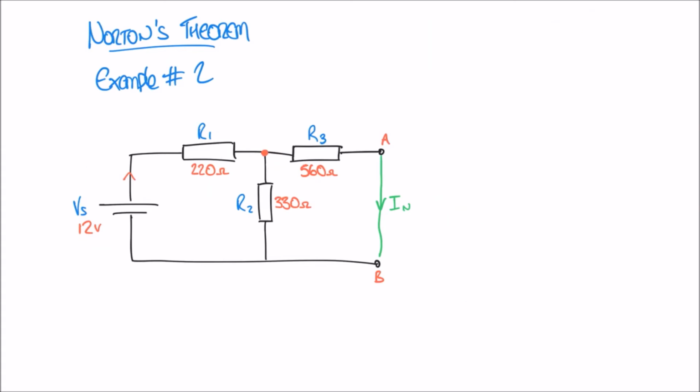So now we've calculated the current that emerges from our supply, and I can mark that on here as IS, and we said that IS is 28.06 milliamps. But what we find is that this current is not the answer to our Norton current, which is over here. The two currents are not going to be the same. And the reason being because IS, the supply current, flows from our supply. It's the current that flows through R1. But then we reach this junction here that we spoke about earlier.